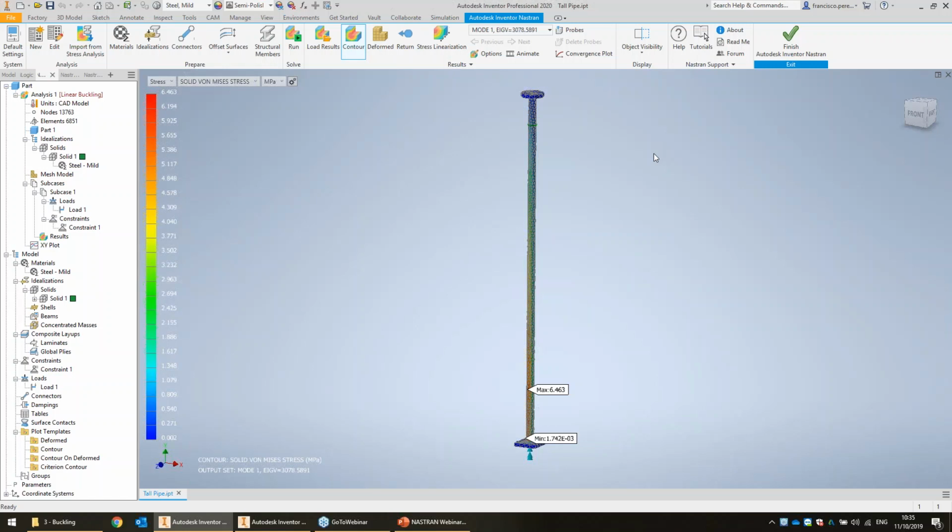The question often comes up, when do we need to consider a nonlinear buckling scenario? A nonlinear buckling scenario is considered when significant deformation in the structure will then yield a buckling mode. So imagine that you're pressing down on this pole and it's structurally sound until it deflects slightly, and then you'll start to get a scenario which is likely to buckle. But those buckling calculations tend to be pretty computationally intensive. So if you can get away with a linear, definitely use linear.